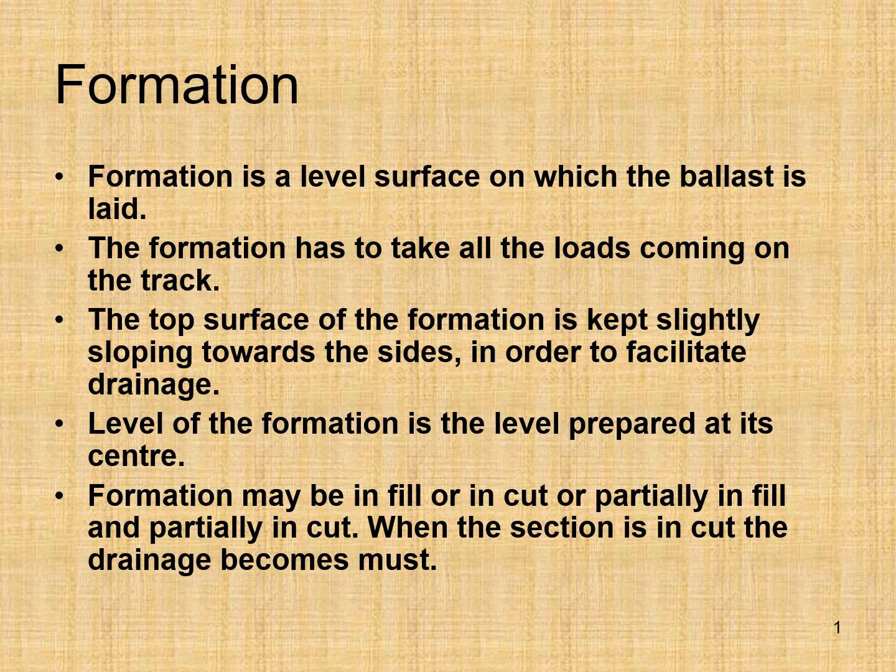Dear students, today we are going to discuss the topic of formation. Formation is a level surface on which the ballast is laid. The formation has to take all the loads coming on the track. The top surface of the formation is kept slightly sloping towards the sides in order to facilitate the drainage.